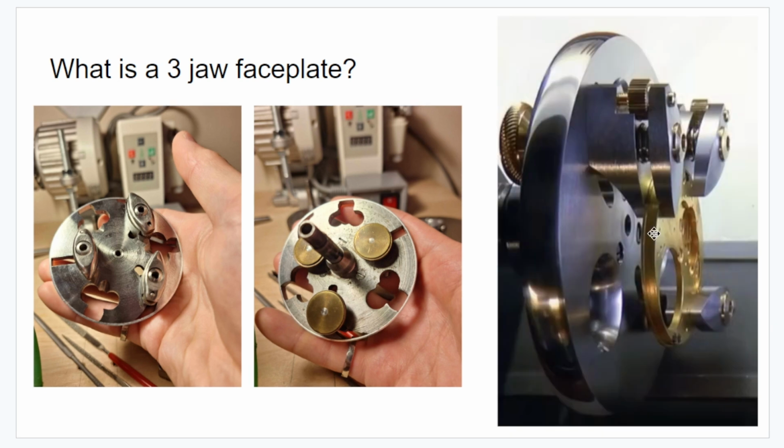So the way that these things work is that the workpiece is held in these jaws and you want the top face of this workpiece to be very perpendicular to the axis of rotation of the lathe. So for that to happen, the workpiece, this top face, has to be parallel to the back face of it. The back face interfaces with this top face of the jaw. This top face of the jaw needs to be really parallel to the back face of the jaw, which is the datum of the jaw. And then this face on the faceplate needs to be perpendicular to the axis of rotation.